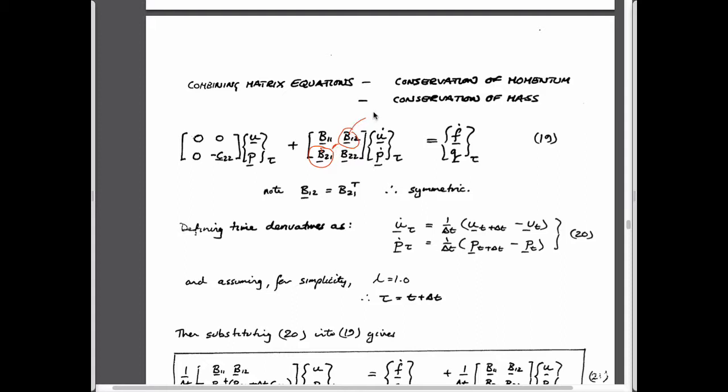So this is alpha dp dx. This is alpha times d epsilon, I guess it's not epsilon dot, is it? It's epsilon. D epsilon, change in volume strain as a function of time. So these are those two terms. And this term is this other term, which in the Biot equation is just 1 over Q, whatever that means, multiplied by a pressure change.